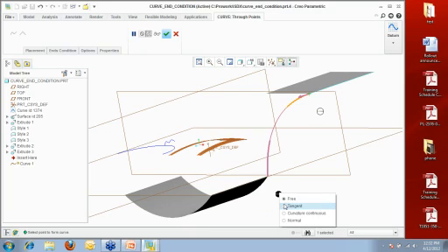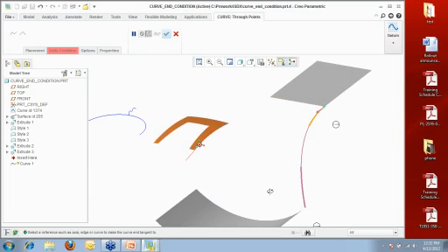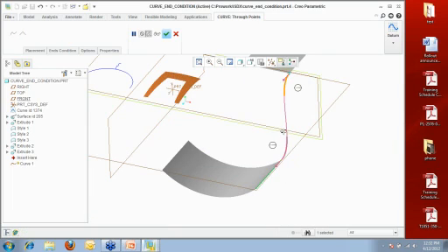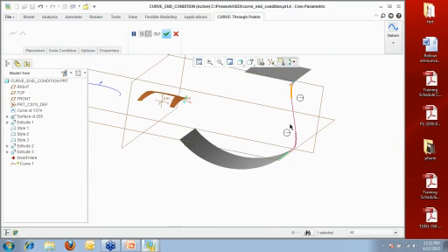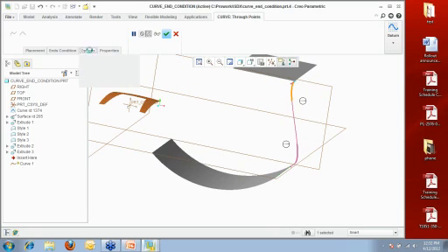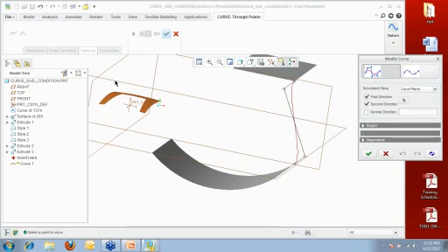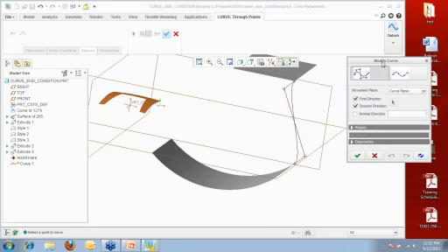I'll right-click on this guy, say tangent to this side, and I want to make it tangent to this edge, and there it is. Great, easy to deal with. You get this tangency, but you're pretty much stuck with the tangency lengths that you have. Also notice how in my options I have this tweak curve, and if I go to tweak curve settings, what does it do? It goes back to the old interface that you've seen in a lot of the previous versions of the software.